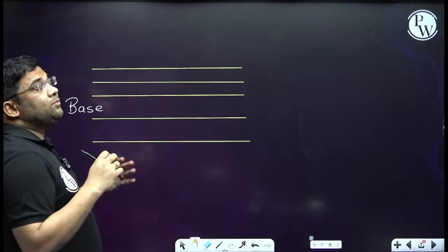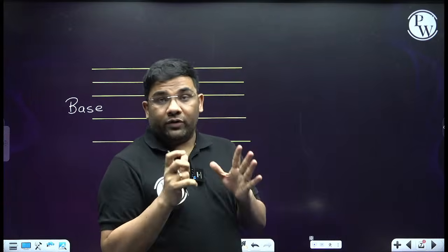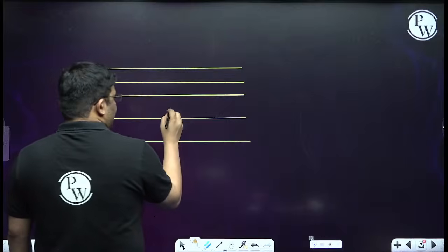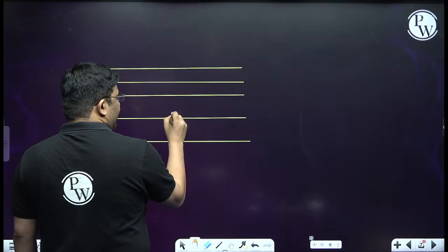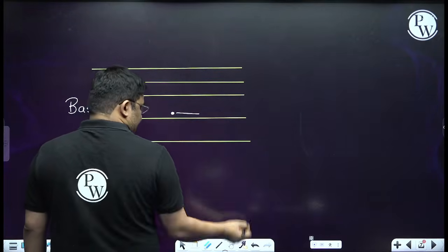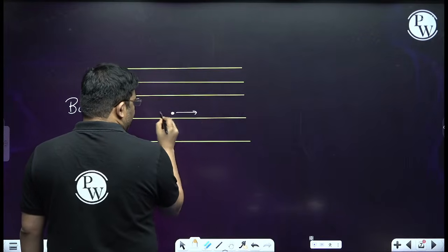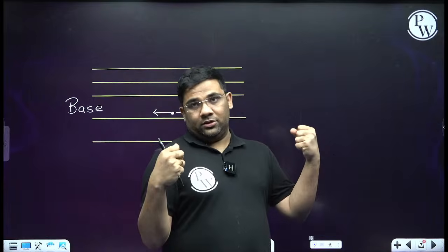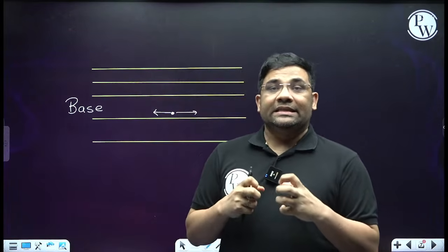The strain responsible for the fatigue cracking is the strain at the bottom of the base layer, and it is horizontal and tensile strain.